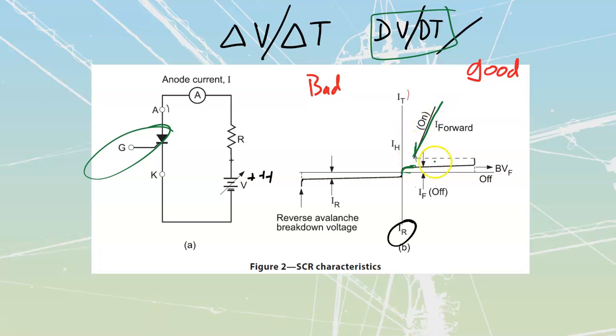They split the graph up actually into two separate things. This one over here, this lower line that I'm going over top, I'll just highlight that one. This one is just what shows what it would be like if I don't use the gate. It would show that I'm going to get a small increasing amount of current as this thing goes along with an increasing amount of voltage. So as the voltage goes up, the current goes up slowly, and then all of a sudden I would reach a point over here where this thing would turn on, and then I would be able to carry a load of current through.